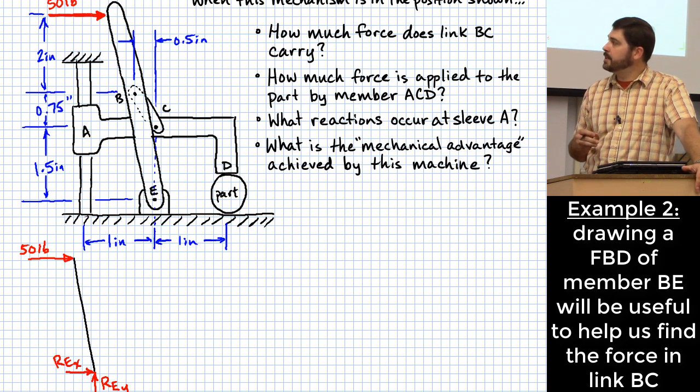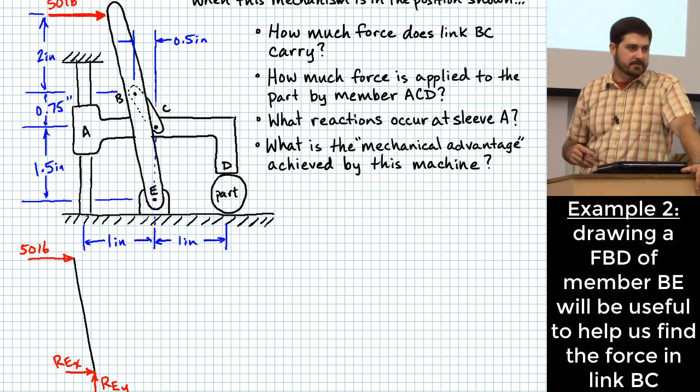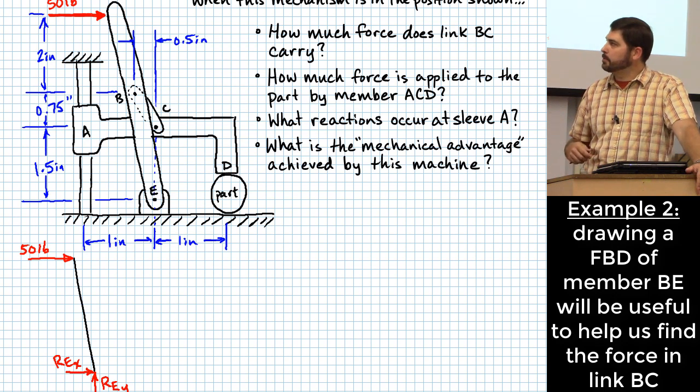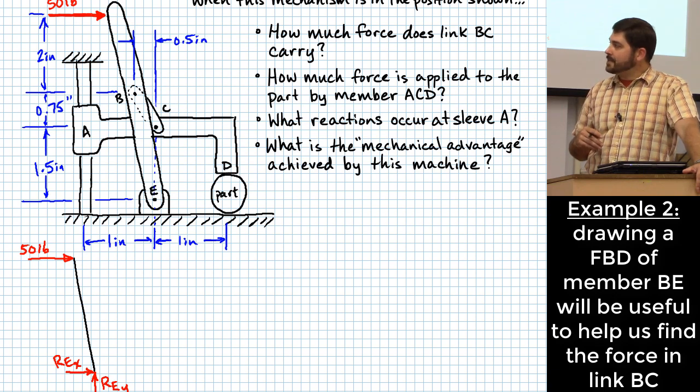Look at it. It's connected at exactly 2 locations with frictionless pins, with no external forces applied anywhere else, right? Besides, really none at all, but no external forces applied certainly anywhere else besides pins. So that is a two-force member.